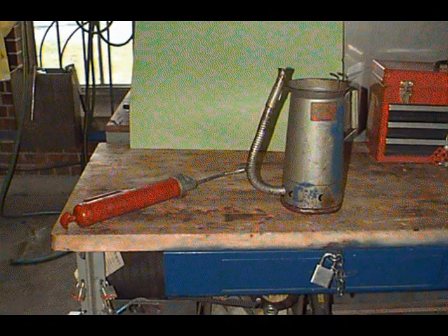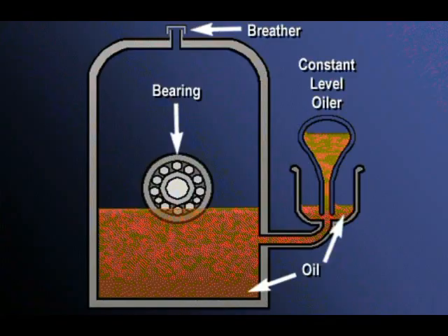As with motor bearings, the shaft bearing units must be lubricated either by oil or by grease. There are several methods of oil lubrication of the shaft bearing unit. For example, an oil reservoir into which the bearing is partially submerged is common on many pumps. Other approaches are to use ring oilers, drip feeders, oil throwers, or a constant level oiler.